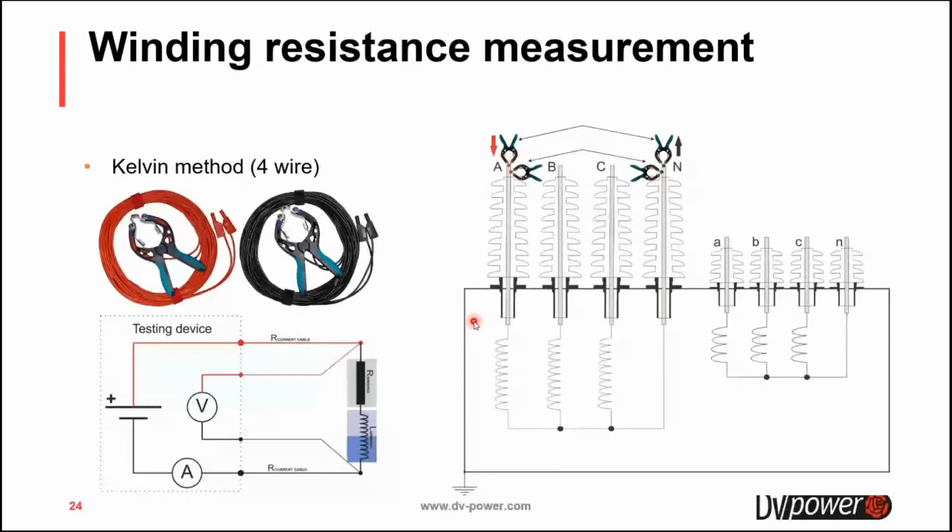All our test equipment uses 4-wire Kelvin measurement. 4-wire Kelvin measurement makes it possible to accurately measure resistance values less than 0.1 ohms while eliminating the resistance of the connected test lead wire. The measurement instrument is connected to the component being measured.